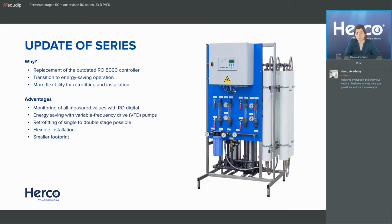The advantages of the new series are we can monitor all the values with the RO digital controller. We have an energy saving version from size 750 on with the variable frequency drive pumps. And you can now retrofit old units, old UOD units, to a double stage. That was not possible before. If you install the Permeate stage series directly, you have a more flexible installation because you have two separate stages, so you can also position them one apart from the other. And for the smaller units, you have a smaller footprint.